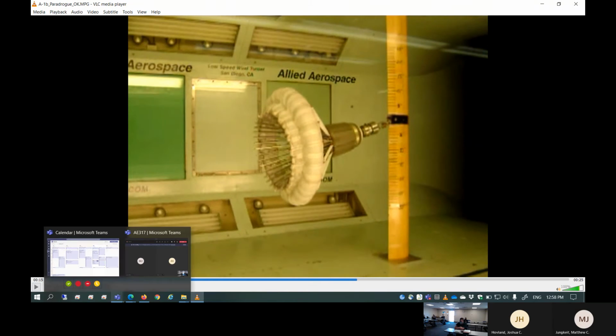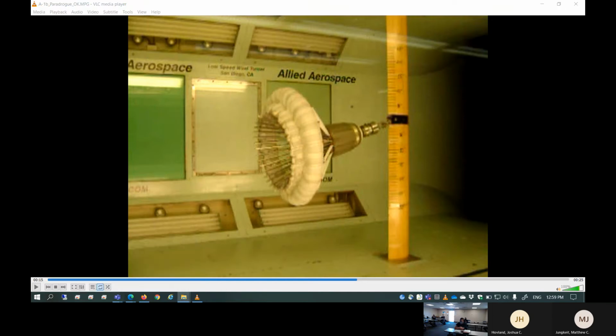If you notice, this is not the regular type of paradrogue. This is a new design. You have 2 different types of parachute cross sections. If it's low speed, both are deflated. If it's high speed, one of them collapses. If you fly at high speed, you can't have much drag; drag needs to be lowered. But if you're flying at low speed, make the parachute surface bigger so that it makes higher drag to open. In other words, in order to open this device, you need drag. This is parachute aerodynamics. So this is a new design, and this flight is okay. However, not so okay, this is fairly unstable.